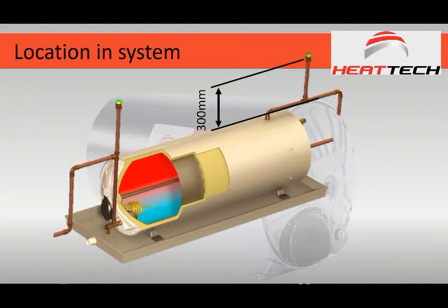That's a good question. I cannot tell you what is available in the industry. I think some of the other people might be more aware of the different types that are available. What I can confirm is that from a standards point of view, various pressure ratings are available and could be allowed. And if you look at the installation standards, it has specific requirements to say that the vacuum breaker must be matched to all the other components that are used in the system.